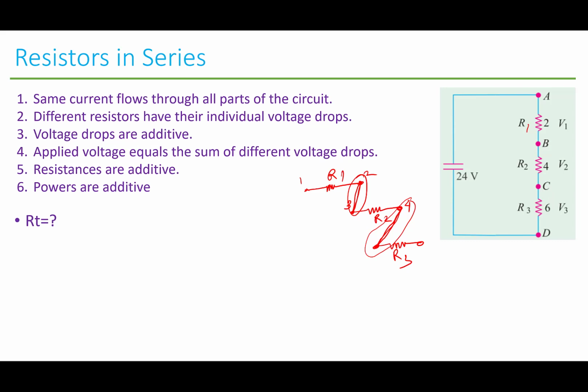So this is not a series connection right here. If we think about something different, so R1 here, R2 here, right? They have two common nodes right now. That means they are not in series connection. Now you know what is a series connection of resistors.